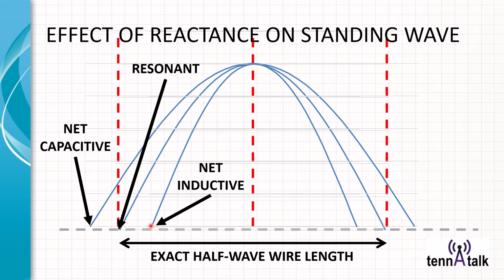And that's how you can accommodate shorter antennas like mobile whips and such like that with enough inductive loading. If you've got capacitive loading like a capacitive hat, then you can accommodate a longer wire for that frequency. Remember, everything is frequency dependent. So this is a way to think about how inductive loading and capacitive loading gets you resonant for that frequency.